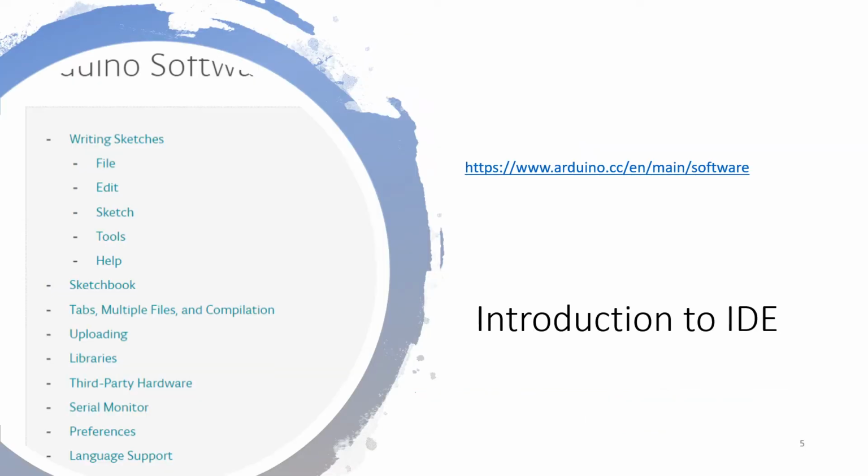The Arduino Mega 2560 can be programmed with the Arduino software. The software can be downloaded from the given link. The Atmega 2560 on the Arduino Mega comes pre-burned with a bootloader that allows you to upload new code to it without using an external hardware programmer. It communicates using the original STK500 protocol. You can also bypass the bootloader and program the microcontroller through the ICSP, that is in-circuit serial programming header. One of the important features of Arduino Mega is the automatic software test.